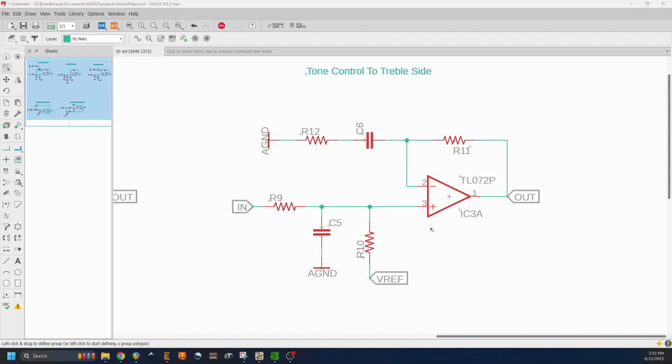You could do a similar thing with transistors, but transistors are a little bit different in how feedback works and everything. But the principle is the same in that we're using these passive components to change the frequency content of our signal, and then using the active element to buffer those, amplify those, and in some cases using negative feedback, actually canceling out some of those.